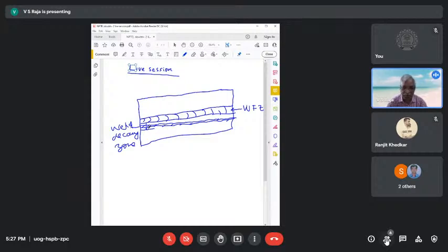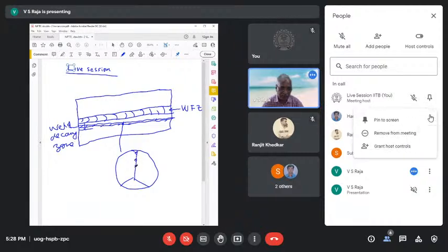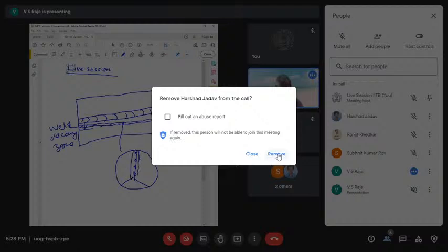Unfortunately, we cannot discuss more in detail, as that comes under welding. But what I would like to say here is that this weld decay zone is characteristic of stainless steels, mostly austenitic grade and ferritic grade stainless steels. In this place there is going to be sensitization. If you magnify this and see it in the microscope, you may see grain boundaries with precipitates, the chromium carbide precipitates, and surrounding these there is a depletion of chromium.